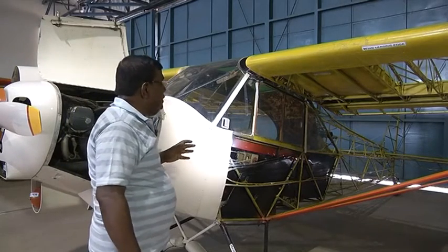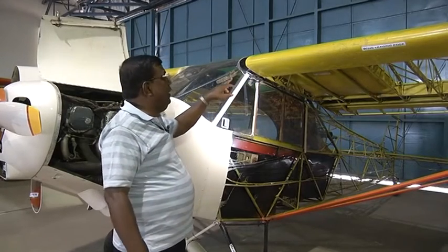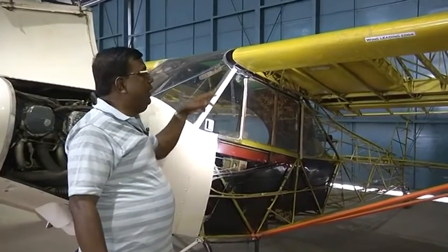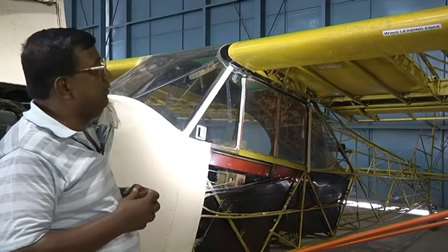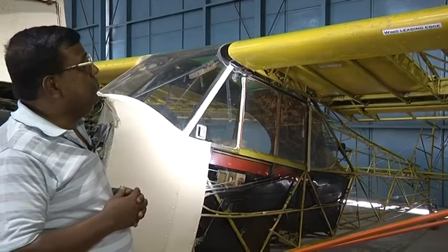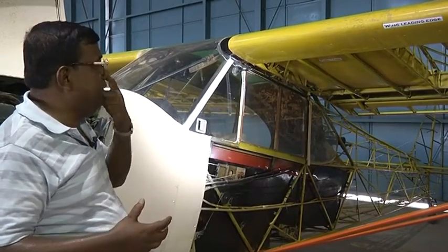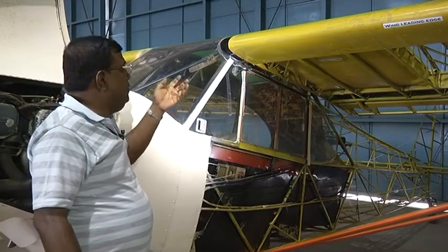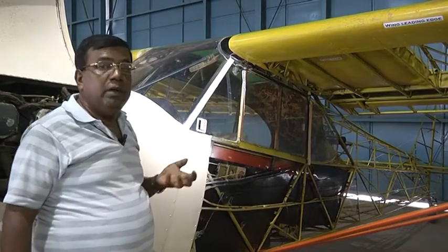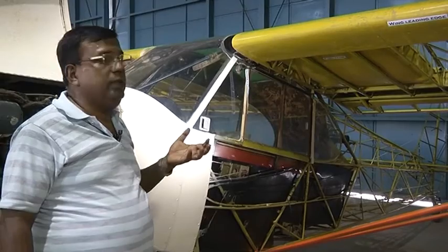So the most important thing we should understand is that we need to cater some space for fuel. The moment I put in a fuel tank, not only is the weight of the fuel important, but it is also important that the fuel tank is leak proof and its weight is not very high, otherwise it will change the wing loading. And we also need to know which fuel pump I'll be using, and the reliability of the fuel pump is extremely important for good performance of an airplane.